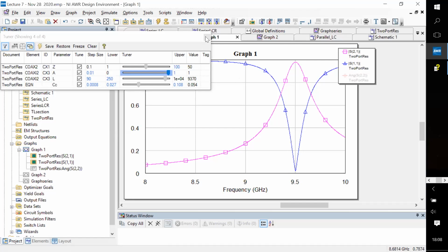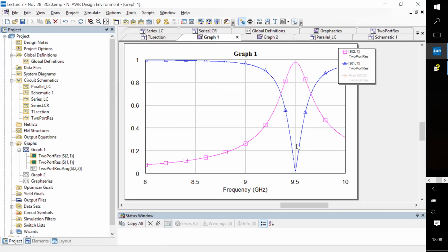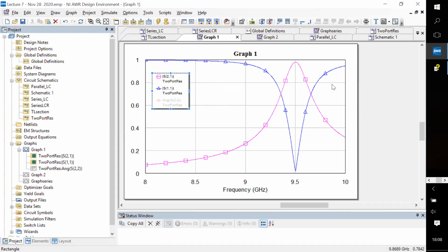Okay, so this is a good place to stop, and we also recognize that these kind of devices are filters because they allow only a certain frequency, a certain band of frequency, to pass through. I guess I missed one other aspect, and maybe I can just mention that: when you have a transmission peak like this, the Q factor is again related to some quantity, which can be measured by looking at how the transmission drops off.